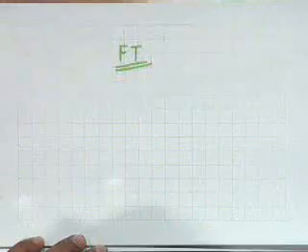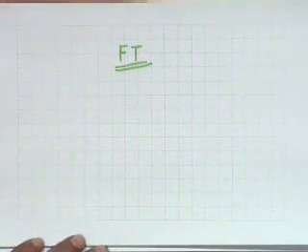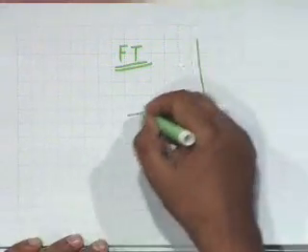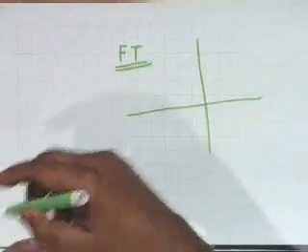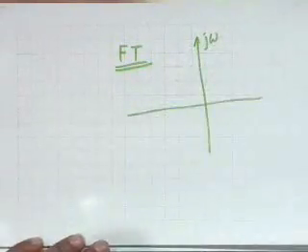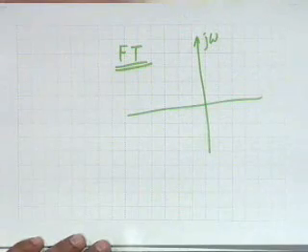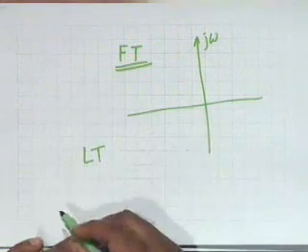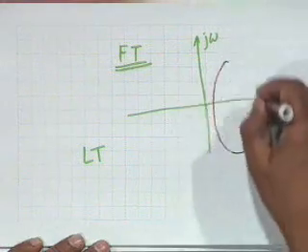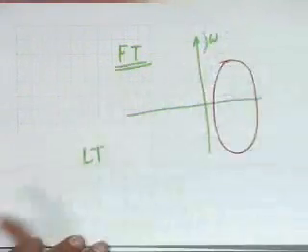That means there are regions of S plane where the Laplace transform converges. At other places it does not. And therefore, this is one fundamental difference between a Fourier transform and Laplace transform. For Fourier transform, you do not have to specify any value of omega, because Fourier transform exists if it exists. When it exists, it is on the j omega axis of the S plane that Fourier transform exists. On the other hand, for Laplace transform, there are regions of the S plane where it exists, and regions where it does not converge.